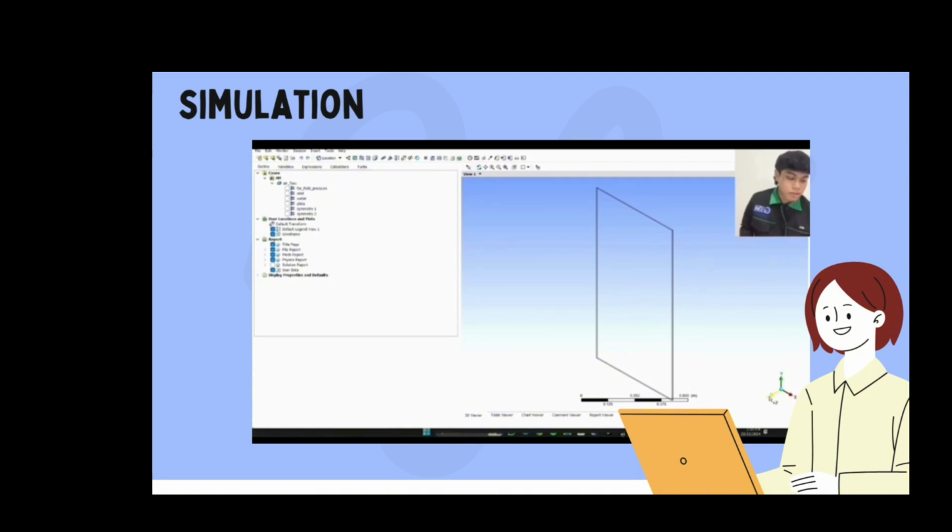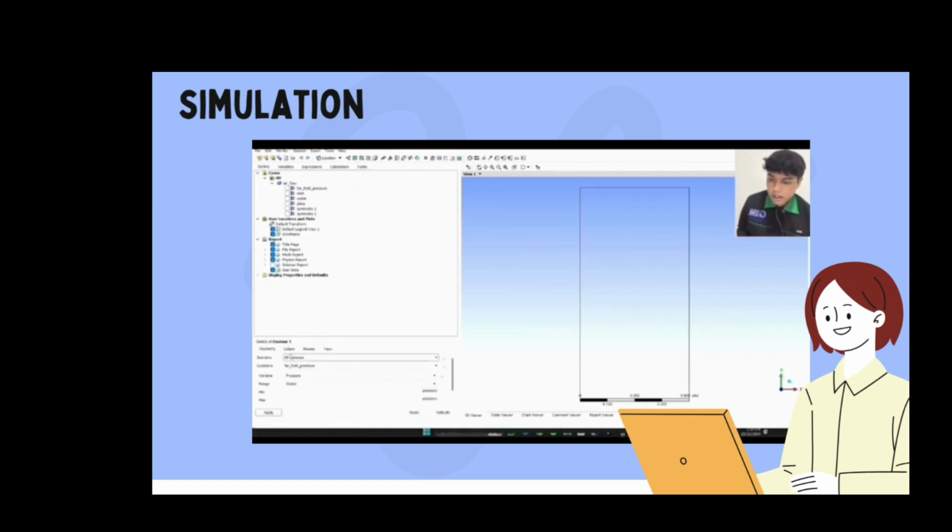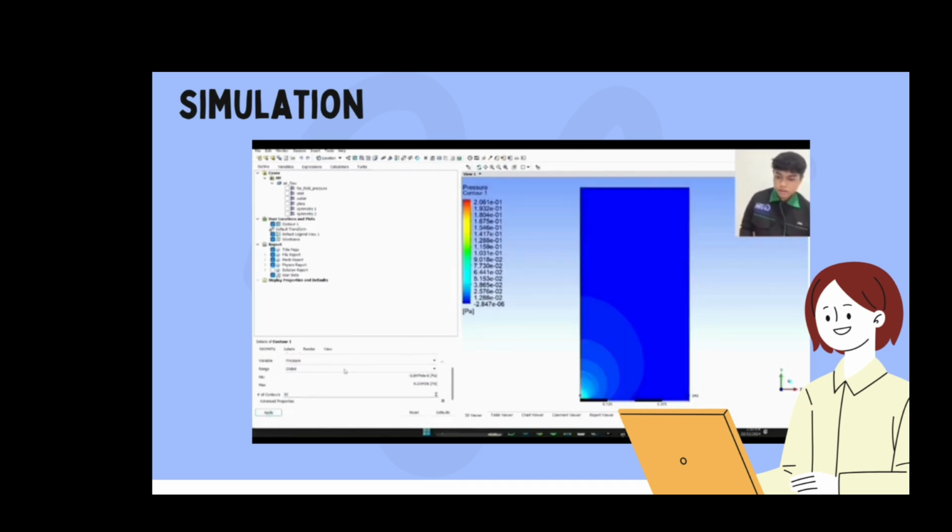So first of all, we make sure we add z axis. So we do add z axis. We go to contour and click OK. We will change the location for field pressure to the symmetry. We change the number of contour to 50. So then we go to velocity to change. This is our pressure diagram. This is our velocity vector.